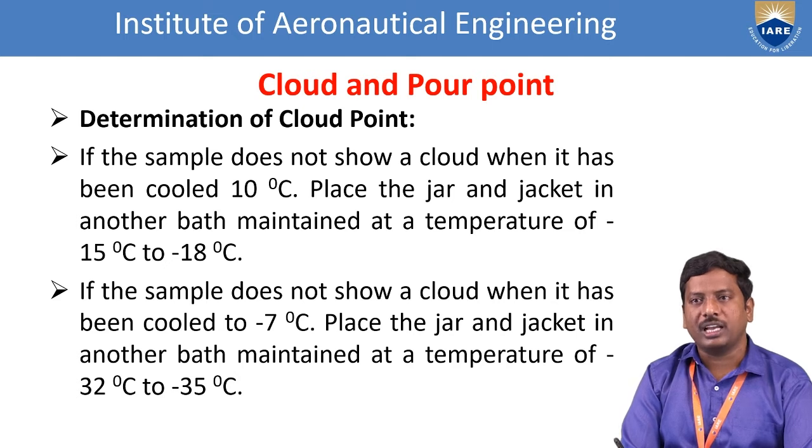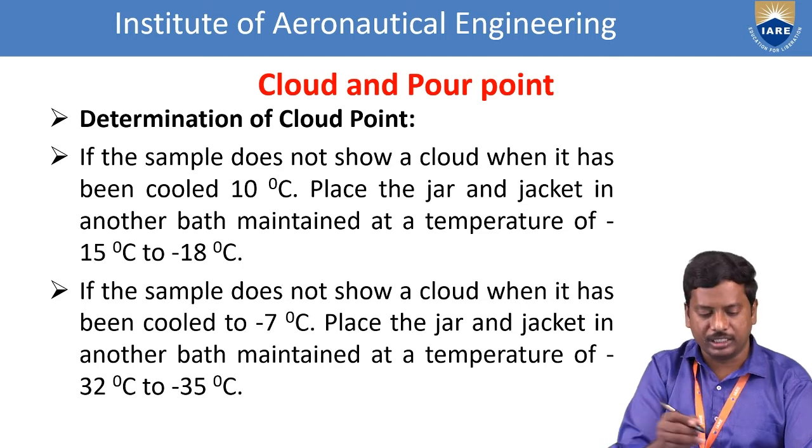That means if the sample does not show a cloud when it has been cooled to 10 degrees centigrade, now place the jar and jacket in another bath maintained at a temperature of 15 degrees centigrade to minus 18 degrees centigrade.